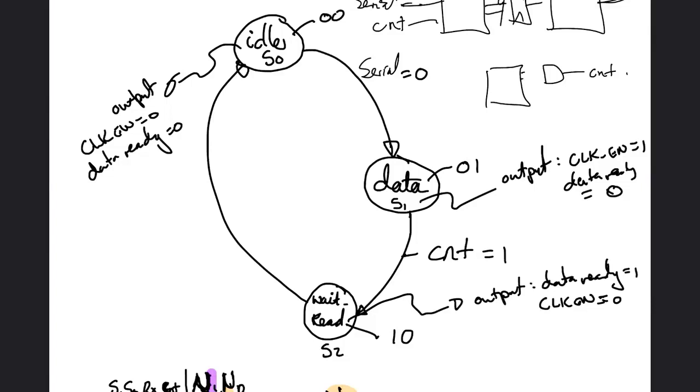then you end up with a truth table, which you need to convert into a Karnaugh map. I'm hoping that you're comfortable converting into a Karnaugh map. Once it's in a Karnaugh map, you just derive the logic that relates the next state and the input conditions. And that's basically what you put in here. So you've got those 2 bits, they feed back here. There we go. So you've got 4 inputs: your receiving line, the serial line, count max, current state bit 1, current state bit 0, and the logic here you get directly from the Karnaugh map. I think that's all I'm comfortable saying at this point, Ms. Malatsi. Is that okay?